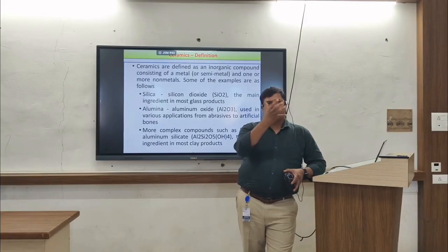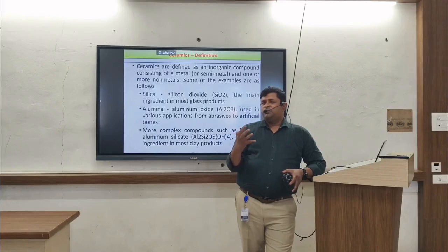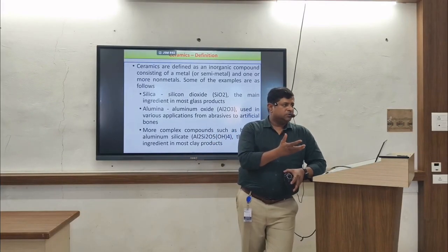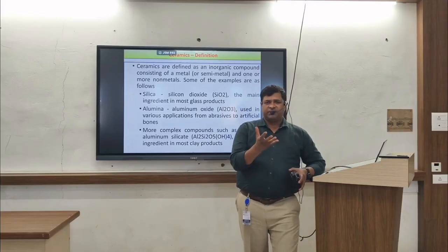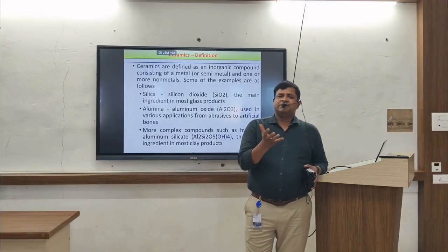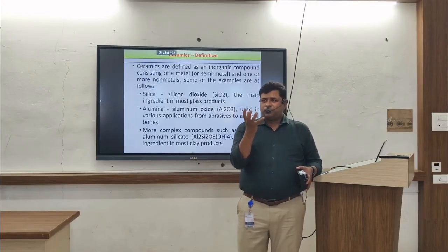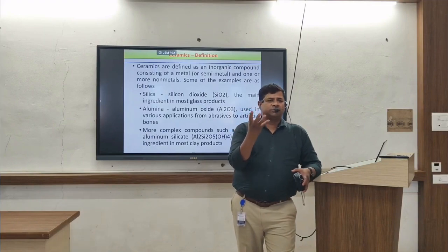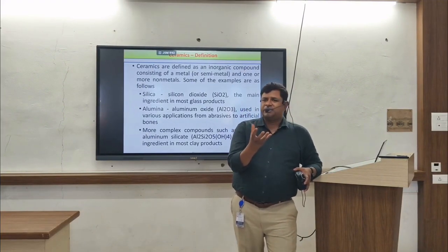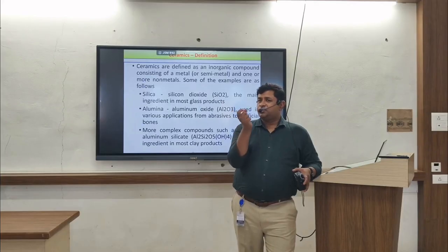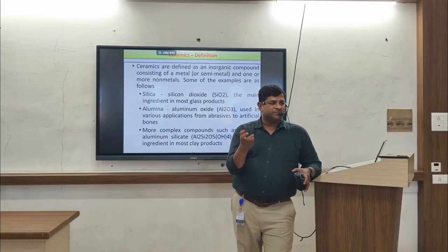If you just dry it in the sunlight, it will not have that much strength. But if you heat it to a certain temperature, like in the preparation of bricks, that is also part of the heating process. Because of heating, the powder particles, which earlier held each other because of water and perhaps some binder, partially deform on heating and become firmly fixed to each other. Therefore its strength increases.